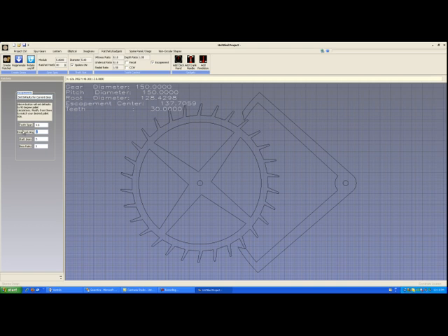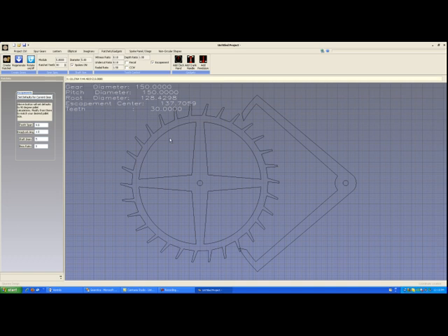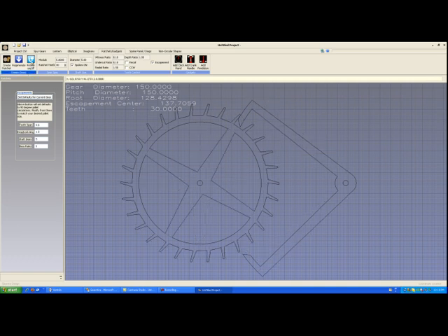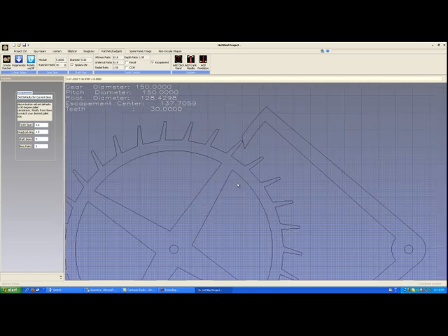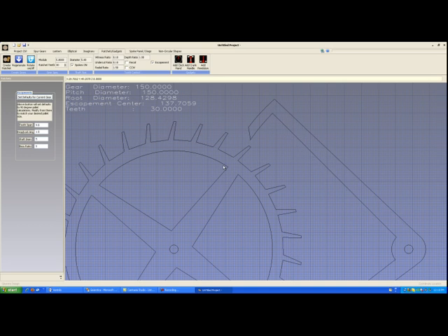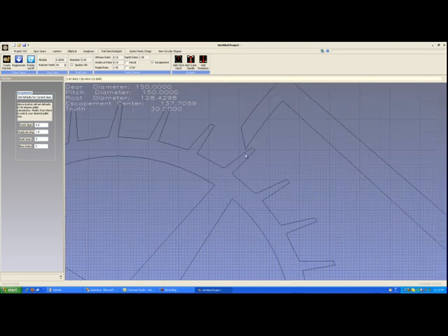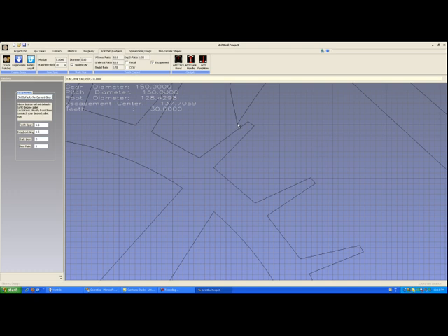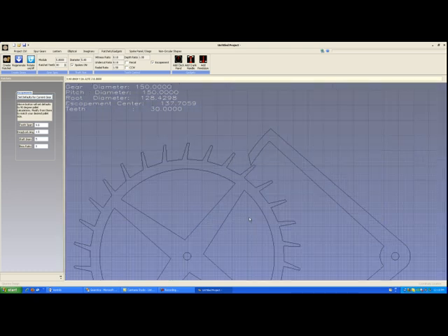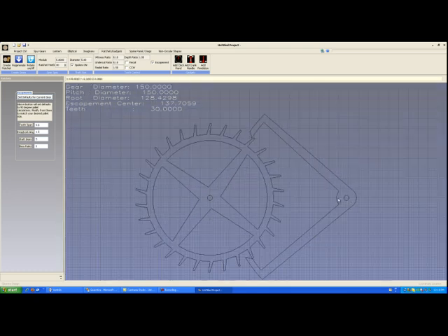By increasing the drop angle to 1.5 degrees, which is typically what I've been using in my testing, you'll see, again, as we watch this tooth come down, and here it comes in, and it's just going to miss this tooth. You can see that the deadbeat has started moving, and we are just over 1 millimeter away from the tooth. This means that we're not as critical as we were a second ago on this centering distance, and it means that the pallet face is about as wide as what you can safely make it.